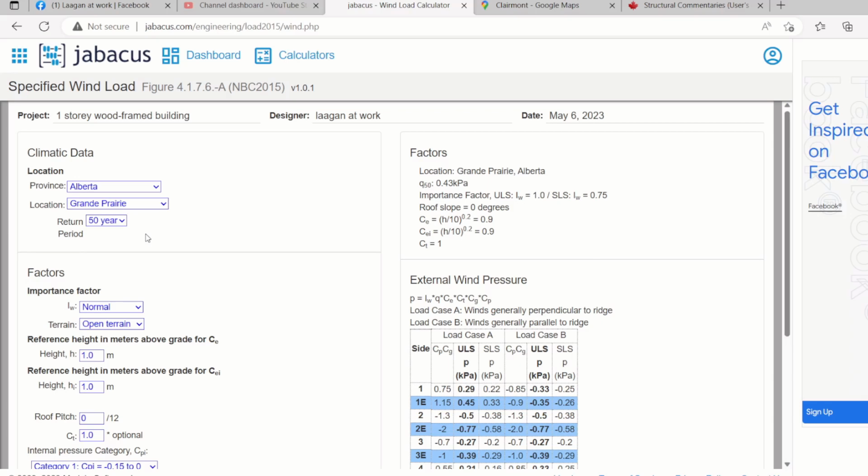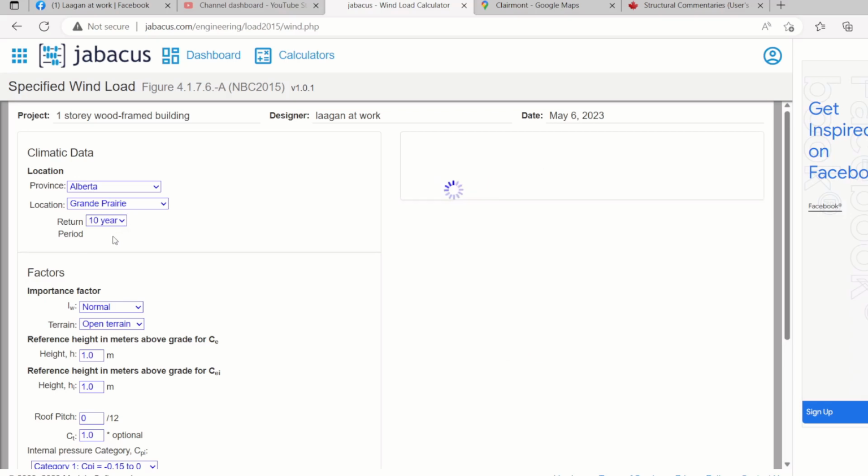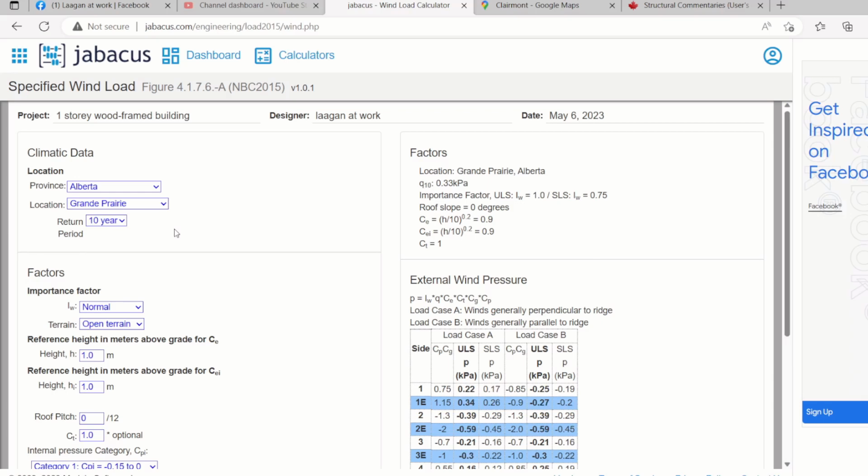So for the wind calculation, for determining how much is the lateral force on your block, like a kick on the structure, then we use the Q10. This one, 10-year occurrence. That's the minimum. So like I said, this one is considered a permanent structure. It is designed until the lifespan of the building.